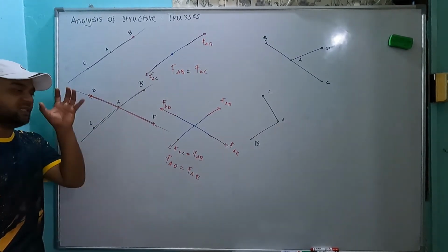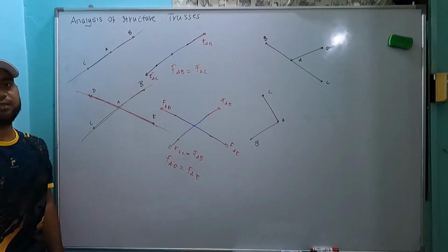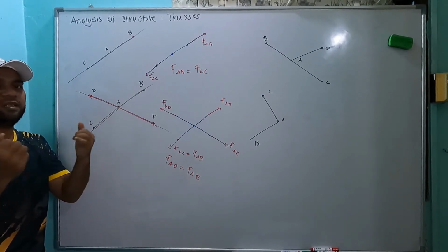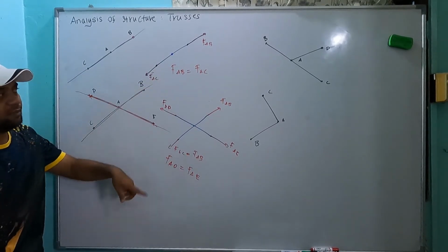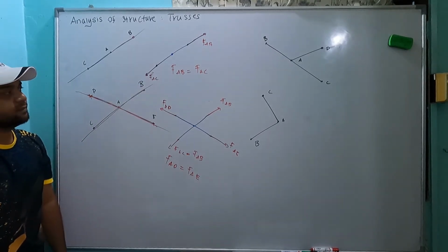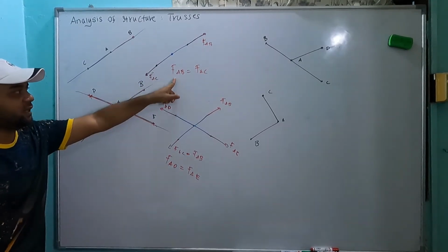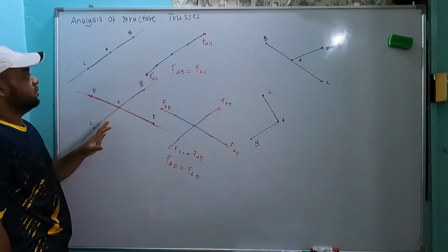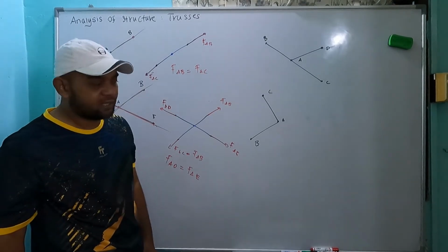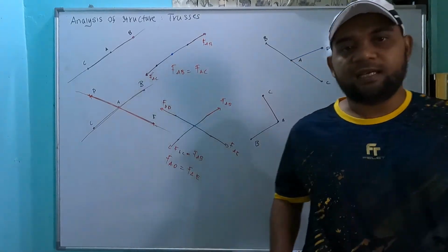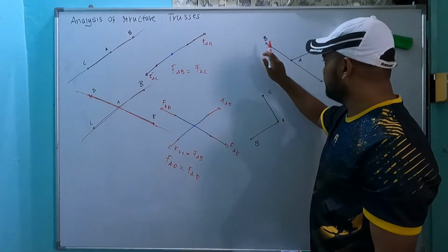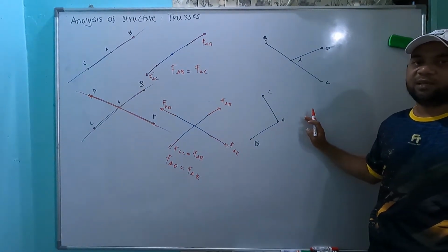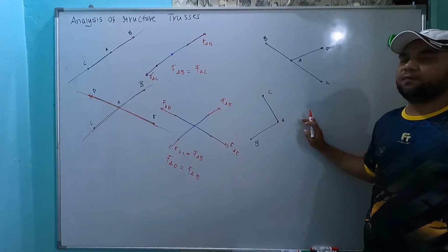Okay, it is the first thing you need to really put in your mind. All of this is a two force member. So the force acting on that component is either in tension or in compression. All of this one, I'm drawing in tension first. Okay, so for this one we have the same here. We have another two. This one is really critical during your analysis, because if you do not understand these two and these two, if you understand this one, you can eliminate a lot of unknowns and save a lot of time.